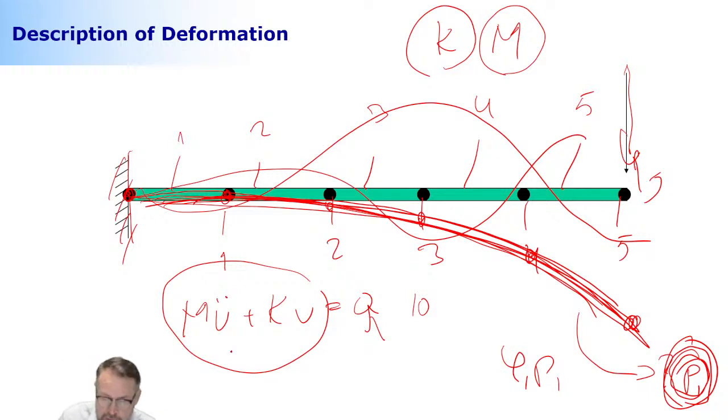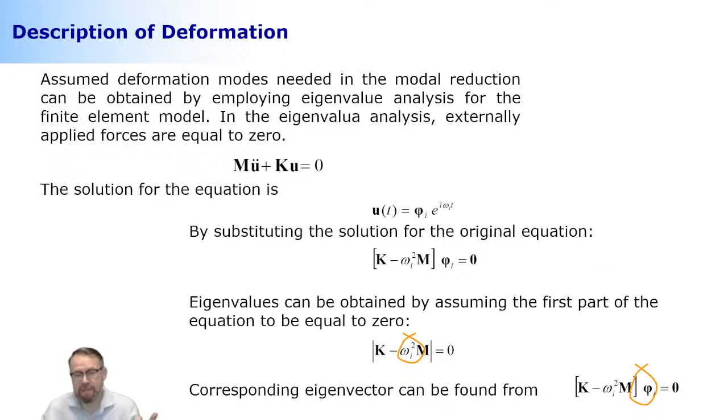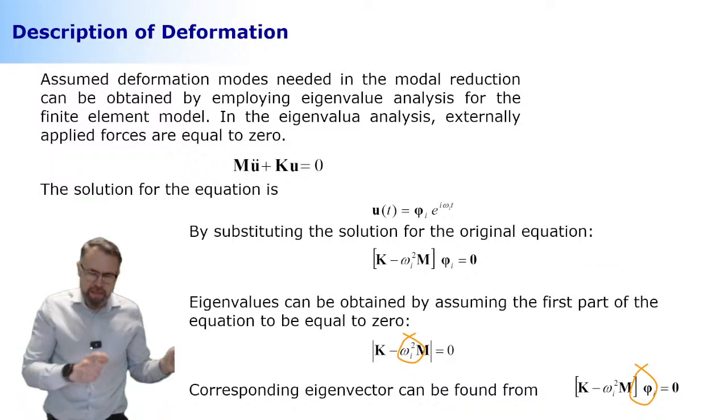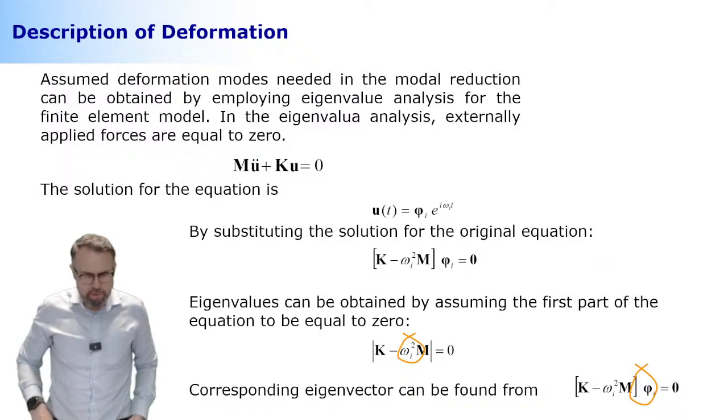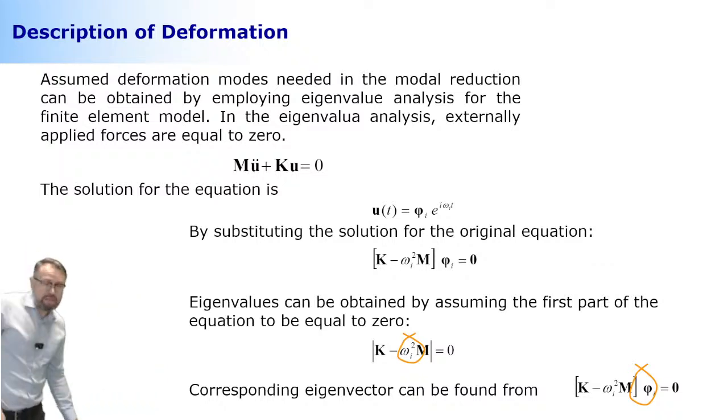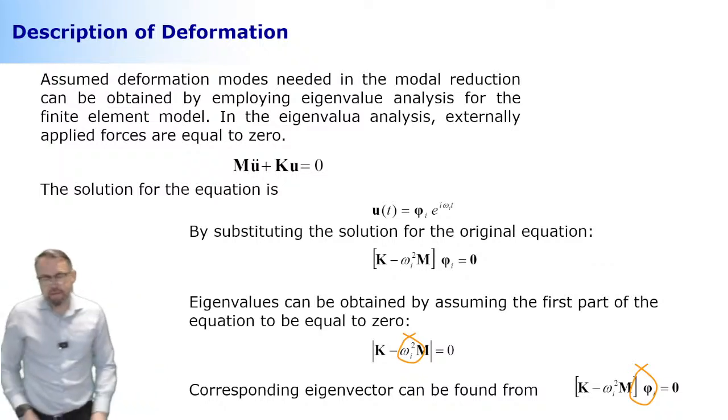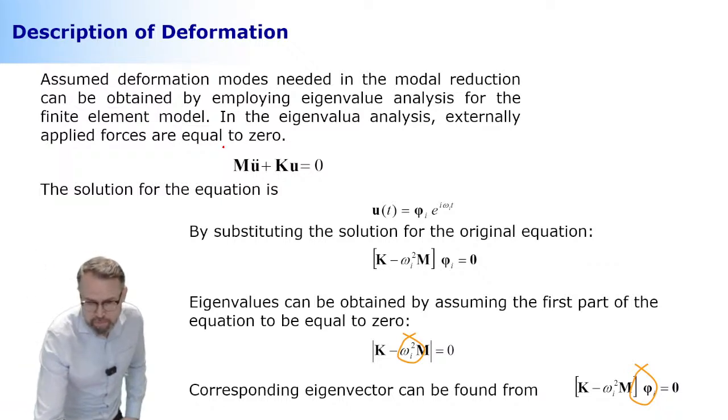Because once we conduct an eigenvalue analysis, it all becomes clear that we're going to get eigenvalues, which are natural frequencies, and eigenvectors. The eigenvalue tells me where the structure vibrates in a certain way, and the eigenvector tells me what this way is. That's what they are. All right, here it is. Let's look at this theoretical background, and then I have a few animations that make clear what the deal is with this. Okay, this is what I just put in writing in my previous slide.